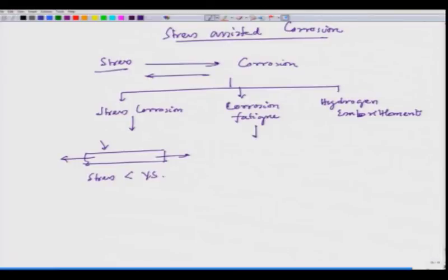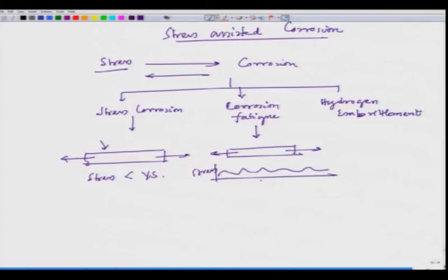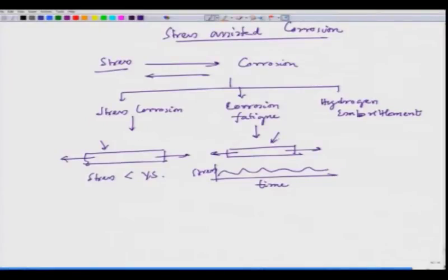But in case of corrosion fatigue, we have a component that experiences alternating stress. So, it can go towards a tensile component as well as a compressive component, and at that time you have a corrosive effect. That particular failure would be considered corrosion fatigue. Just like what we experienced in the case of the Silver Bridge, as we gave as an example in the first lecture. So, people think that stress corrosion as well as corrosion fatigue were the two culprits for the catastrophe in that bridge failure.